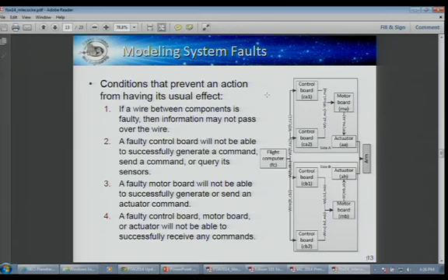You're writing logical representations of these rules, basically, saying that in the absence of a fault, flight computer FC can send a message to control board CA1, and the result is CA1 has the message. And then you have another rule somewhere saying, but if the wire between the two is broken, the result is CA1 does not have the message. So it's all very simple, when you're specifying how this works. It sounds kind of dumb, but once you've got it all specified, now the computer can reason through all the different combinations of what happens. So that's where the power of it comes in.